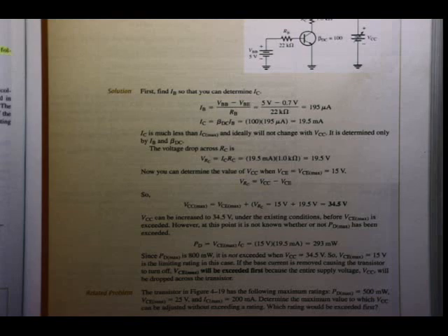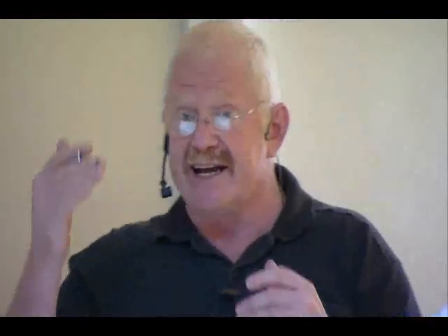So if the power dissipation rating of a specific device was, say for instance, 1 watt at 25 degrees Celsius, it won't be able to do 1 watt at, say, 75 degrees Celsius. It will have to be lower now because the surrounding temperature is much hotter. So I have to go and work out the derating factor. And that is also something that I will get on the data sheet.